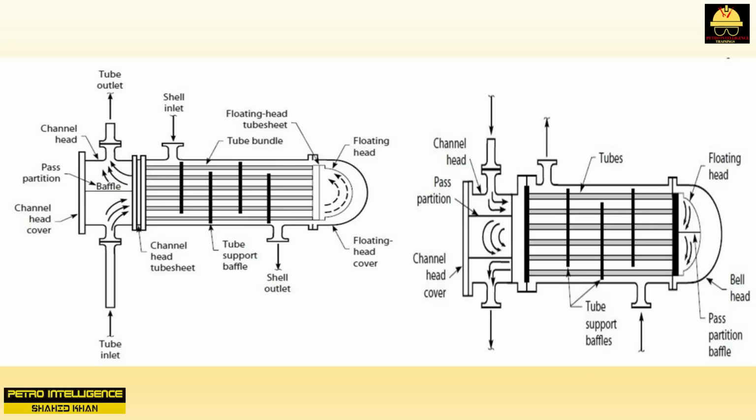Quite likely, even after several years of operation, the pressure drop of a 4-pass exchanger will be greater than the delta P of a 2-pass exchanger in the same service. Quite likely, the initial U value of a 4-pass exchanger, days after it has been returned to service, will be only slightly higher than the U value of a 2-pass exchanger. However, the 4-pass exchanger will maintain its U value with time far better than will the lower velocity 2-pass tube bundle heat exchanger. The 8-fold increase in pressure drop is certainly a stiff price to pay for this improvement in the long-term U value. But remember this: it is the clean delta P of the tube bundle that will increase by a factor of 8.